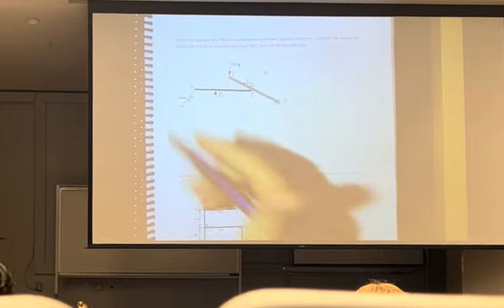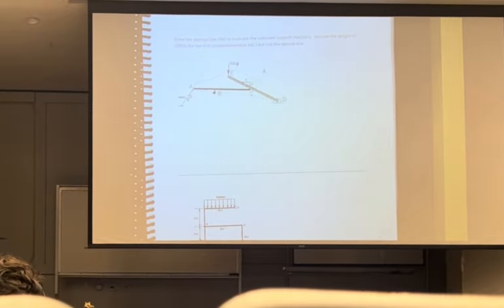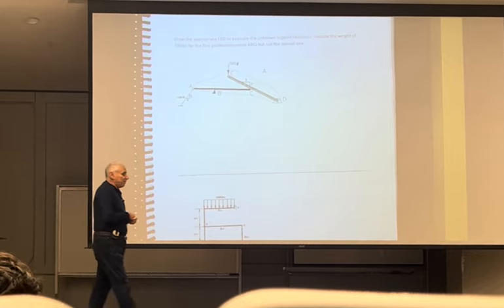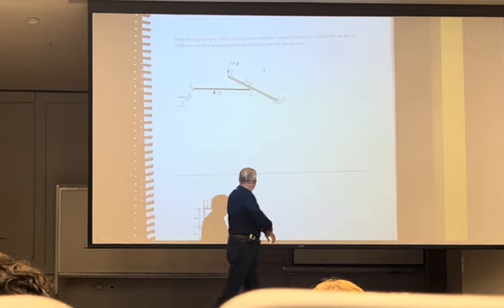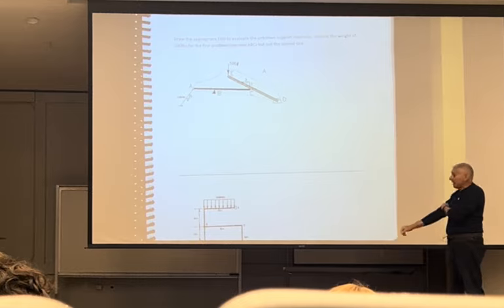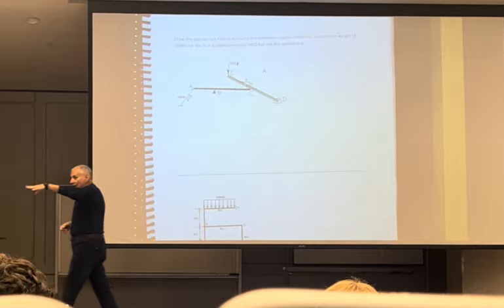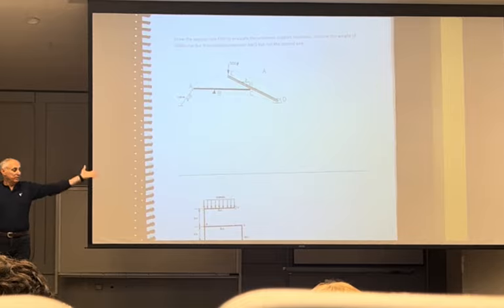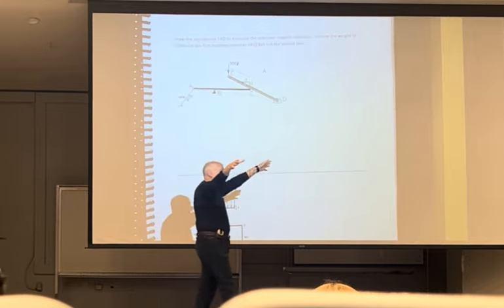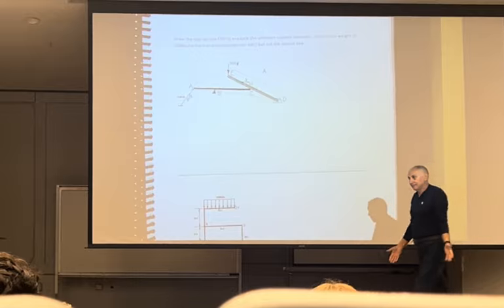We look at this and we say, all right, I want to draw a free body diagram of this. If I do this, it will be a free body diagram, but it won't be appropriate. Why won't it be appropriate? Well, because I will have touched the cable at A, I will have touched the pin at B, the pin at C, at D. That's 2 for each pin, that's 4, and the cable is 5 unknowns. I only have 3 equations, 5 unknowns, I can't solve this. It will be a free body diagram, but it's useless to you because I can't solve for everything.